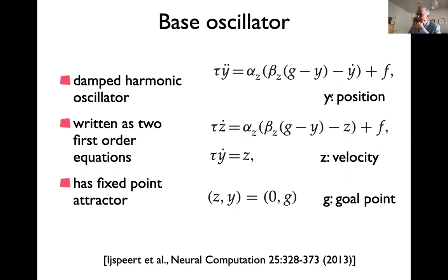So the variable here is some one-dimensional position of some planned end effector trajectory. You see here's the second derivative. Somewhere in here is an elastic term that is only proportional to the y, the position itself, with a negative sign. That would be like a spring, right? A stiffness kind of parameter. So if nothing else was here, then you would see that this is a spring with length g. So if nothing else, you would have zero acceleration if your length is at g, and g will then later be the target value. So that's where you will make the attractor.